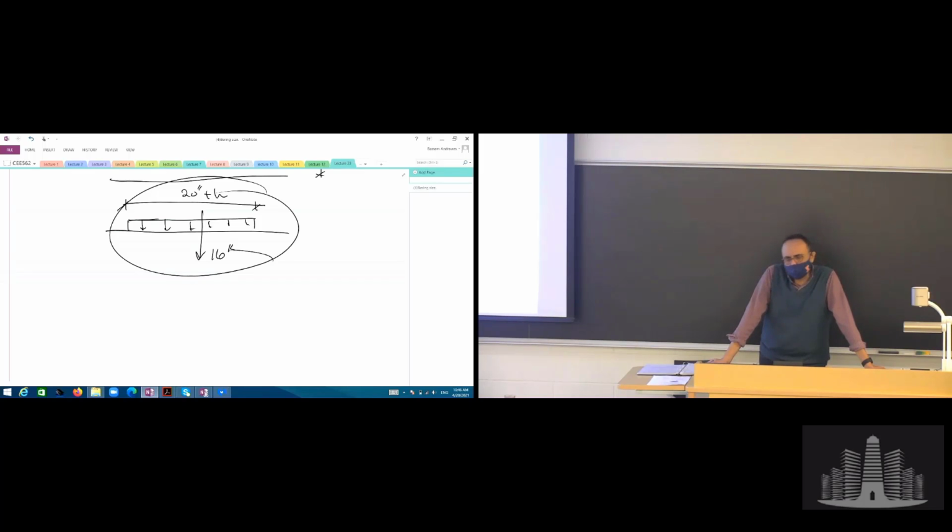Sometimes we tend to use this when, for example, we are checking the rating of a bridge, and we are a little bit tight on the rating. I want to grab everything possible just to see if it's going to work or not. Be more realistic, in other words. Then we can actually go with a pressure distribution like that.